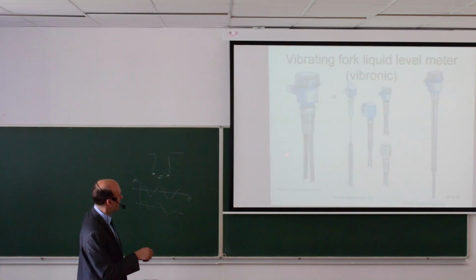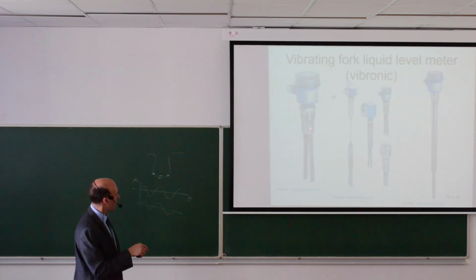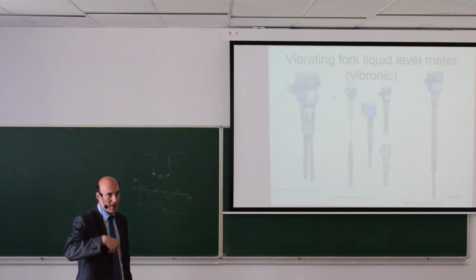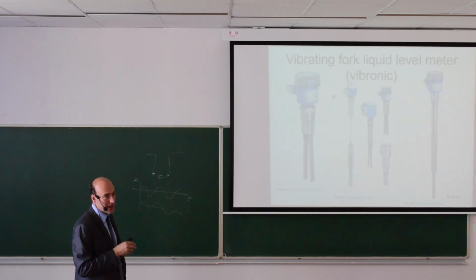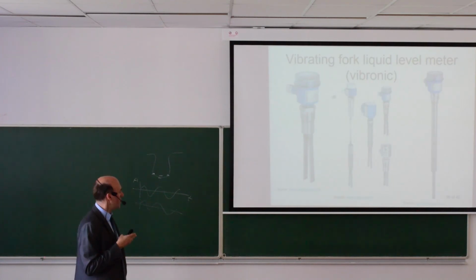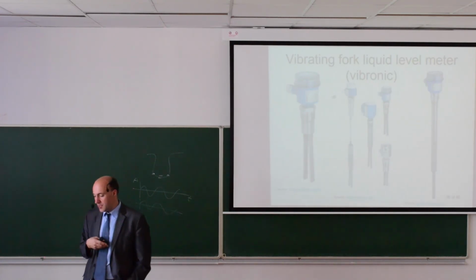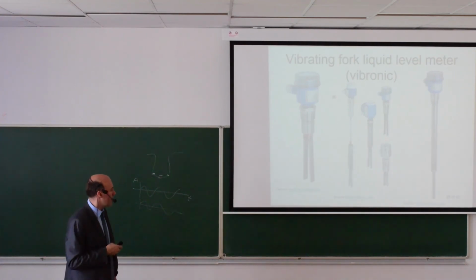So those sensors are for solids. They have a longer fork, and here is the piezoelectric stack. You can also have it extended on a kind of chain, and this is then placed into the silo and detects the summit of the material if the silo is full.